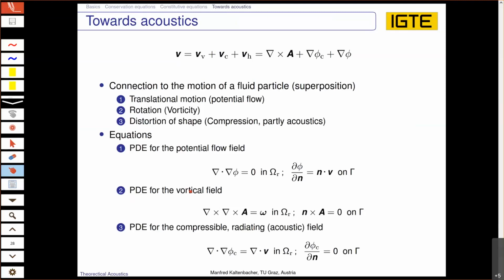For a lot of problems, like I have explained to you, just a ventilator or a compressor, turbocharger noise, and so on, very often you need at least 2-3 weeks just for the flow computation to have really reliable results with which you can then go into one of the models we will discuss and compute the generated noise, the generated acoustic sound.